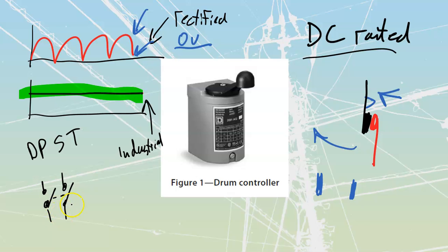Downstream of that, inside of these switches, you can incorporate overload devices. Those overload devices are simply going to be heaters that are then going to send out a trip signal that's going to be able to trip out that switch over there. Once again, the overloads themselves do not open themselves.